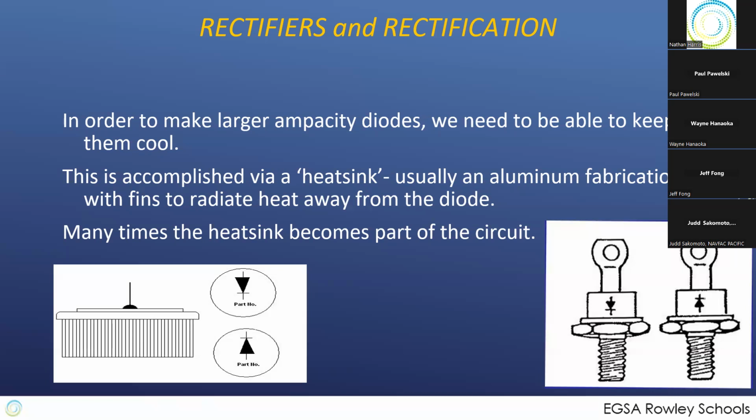If you take something like this on a machine that's in Camp Lemonnier in Djibouti, where it's above 100 for multiple days of the year and it stays very hot all the time, the insulation's most likely breaking down, which means eventually all of that aluminum becomes part of the circuit, which means it's not only hot physically, it's hot electrically. And it's another good way for you to get, if you're lucky, only a nasty shot.